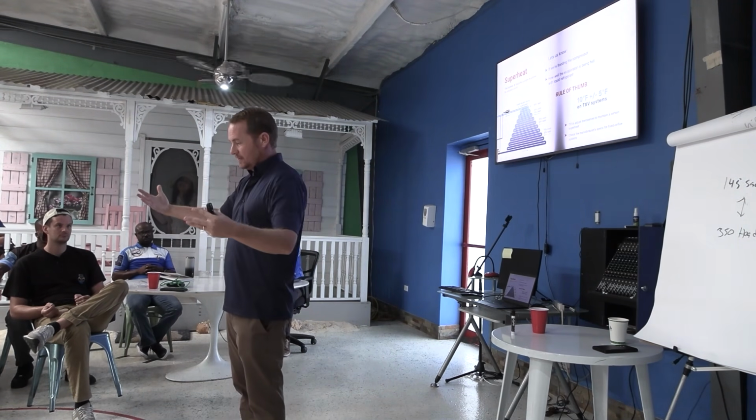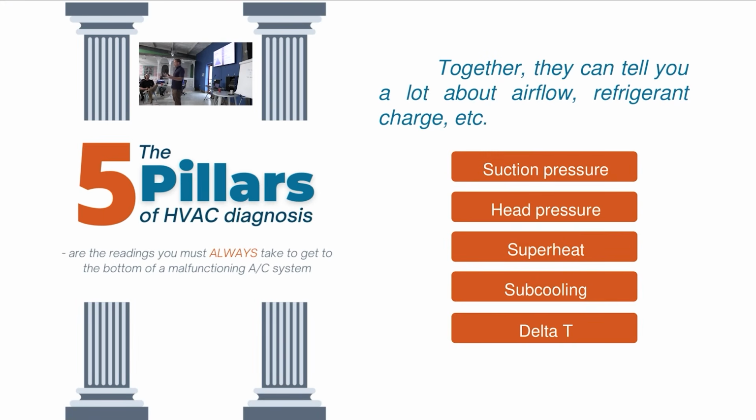So we have to always, and again, you have to stack information and information. When you look at the 5 pillars, they only work if your temperature clamp is reading properly, your pressure probe is reading properly. You know that it could be different inside or outside. Same thing's true of the liquid line, right?